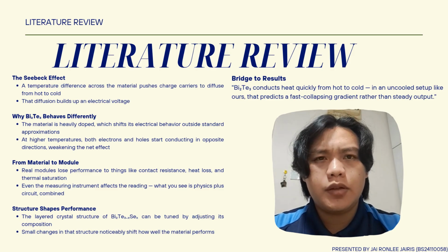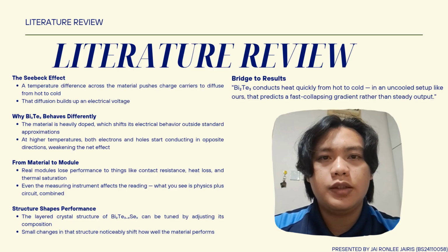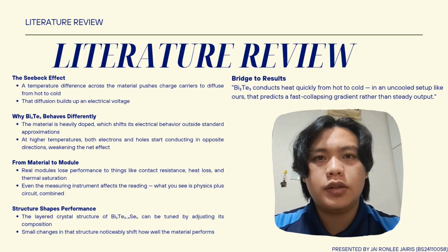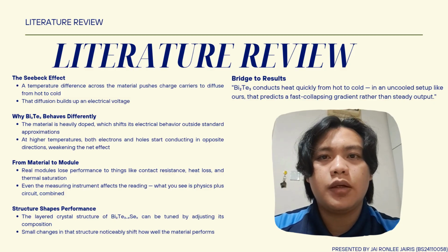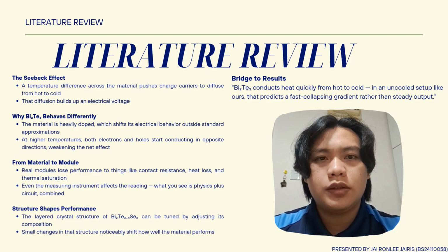The specific material we use is bismuth telluride. It is heavily doped, meaning it is engineered to conduct electricity efficiently. However, this material has a major limitation at high temperatures, where both positive and negative charge carriers start moving at the same time. They partly cancel each other out, causing the material to lose efficiency as it gets hotter.